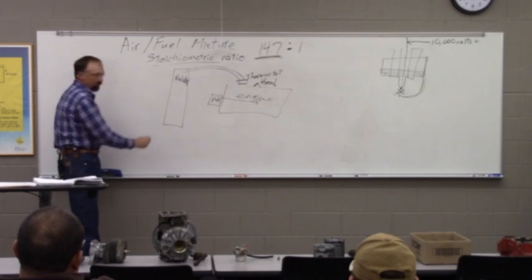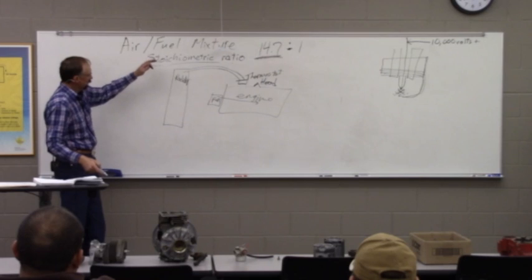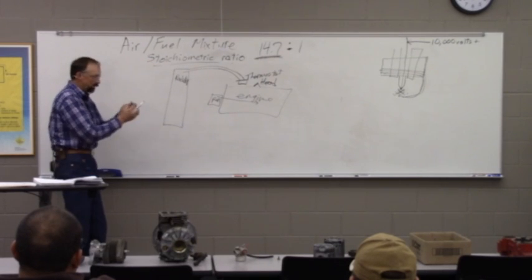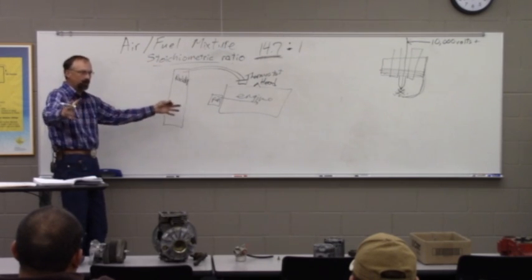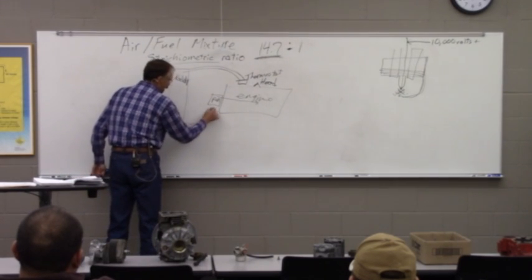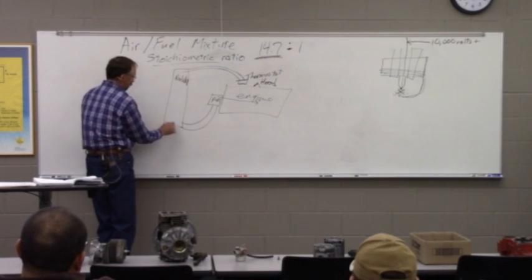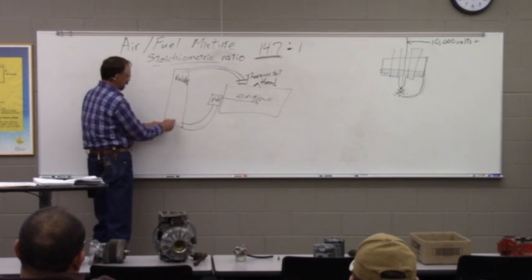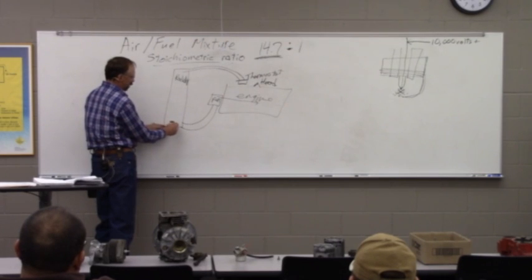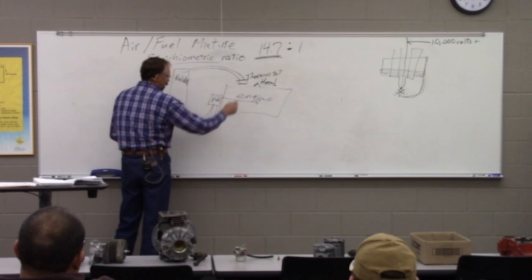We're going to go down through the radiator doing what we talked about there. We're going to transfer the heat from the liquid into the metal fins, from the metal fins out into the air, and then the water is going to come from the bottom of the radiator, which there again, because heat rises, our coolest water is going to be here in the bottom. It's going to come back into this pump and be circulated back through the engine.